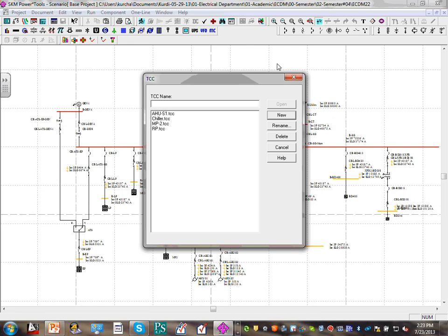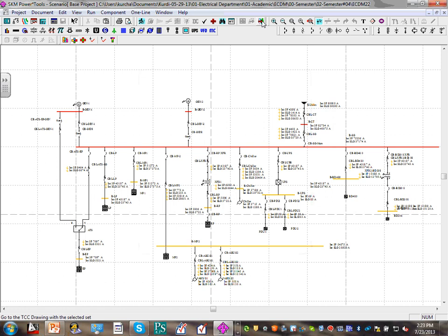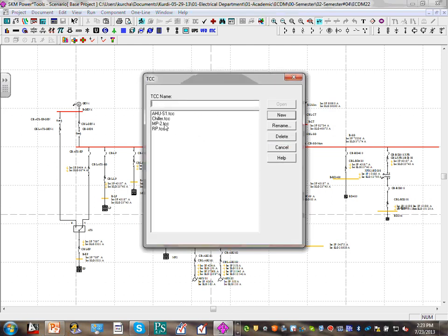I'm going to go, guys. Here's the arc flash. When it comes to the overcurrent protection devices, the single most important thing after you size them properly for safety is the survivability of the system. The worst thing that could happen to you is you walk into a building, a short circuit on a light trips the main. That's a bad day for us as engineers and everybody else.